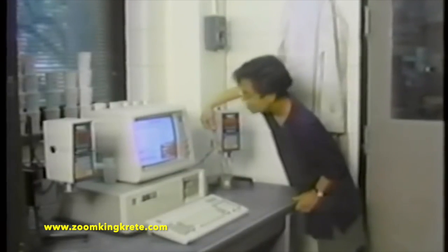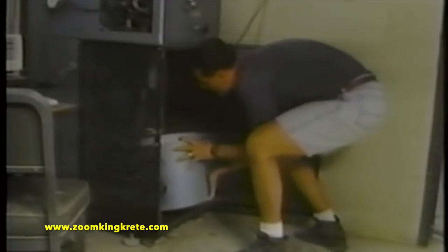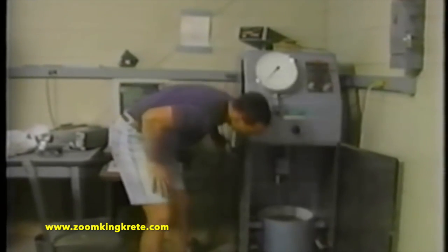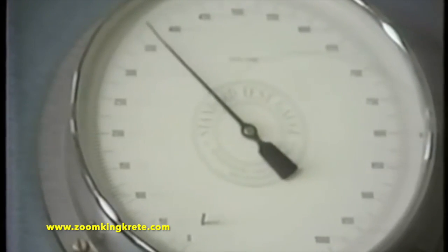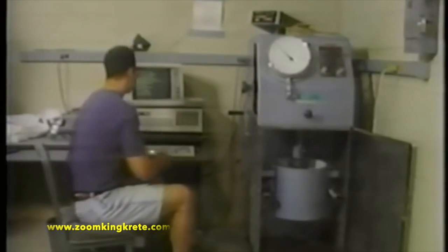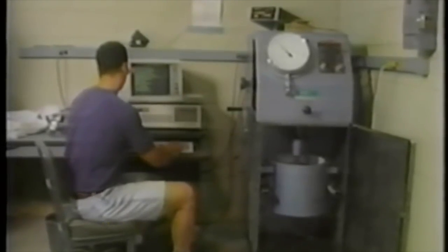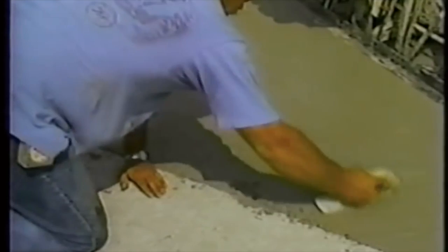In the lab, fluid properties of cement paste can be measured with this Brookfield rheometer. Researchers use larger equipment, such as this Tattersall rheometer, to measure the properties of mortar and concrete. The rheological equipment can be used to measure the initial resistance to flow, which is referred to as yield stress. At the time of setting, the yield stress starts to increase abruptly, and the ability to flow is lost. Researchers are interested in flow characteristics to understand how the process of hydration stiffens the fresh concrete and leads to set in the concrete.